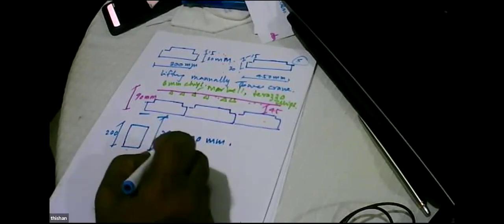The beauty of this system is because there are beams and the overall thickness is precast at 200. Then we complete at 300 millimeters, 290. So these are beam-slab systems. Generally, the delta is pretty close to 0 in these systems due to the dead weight. So the deflection is almost 0.